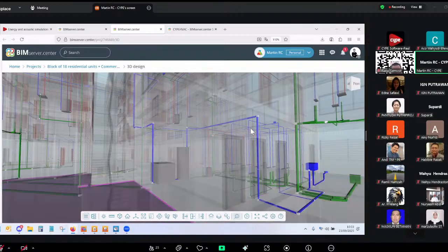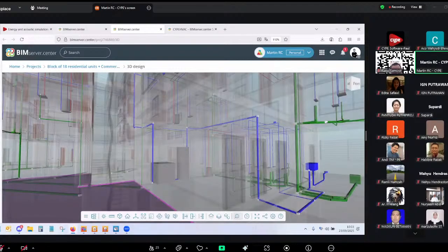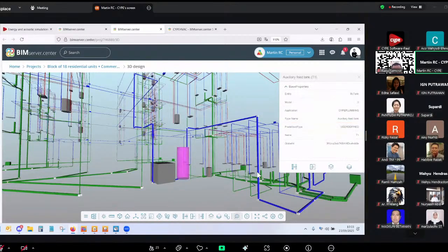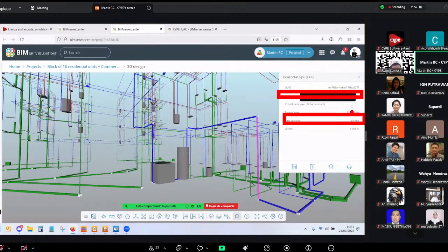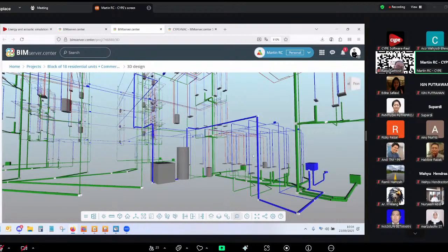visibility of, I will even hide the building so that we can see that we are actually watching the ID of the BIM element, the type name of that, the fit tank, where has it been generated, this pipe, diameter, material, length, right? And this diameter is this because the hydraulic analysis says it is needed for the supply of this building, right? And according to the code that we've used, in this case, a UK standard, right? So this is completely professional output.